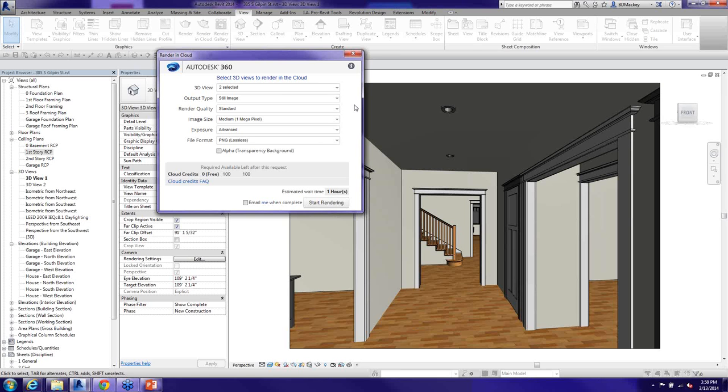In Revit, you're rendering one view at a time. So you can be like, I wonder which one of these is going to look better. I've got these 6 cameras set up, slightly different angles of the building. I wonder which one's going to look better. Render all 6 of them at once. Walk away.